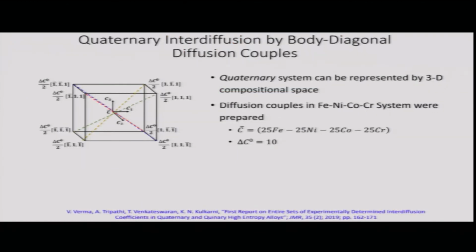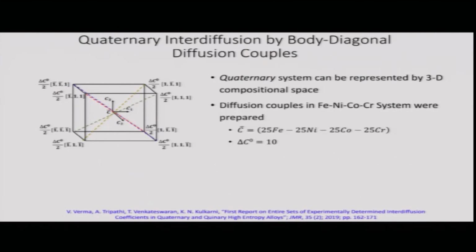We have also applied the body diagonal diffusion couple technique to evaluate interdiffusion coefficients in Quaternary and Quinary system. So, let us look at the Quaternary system first.